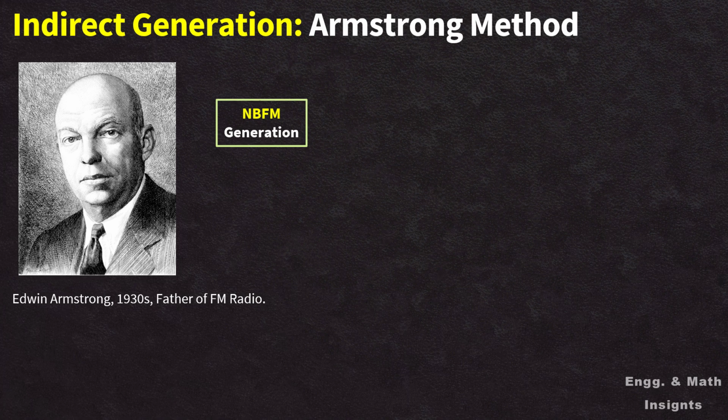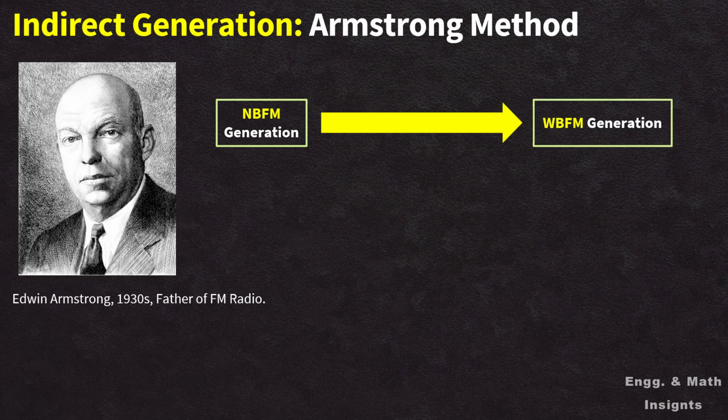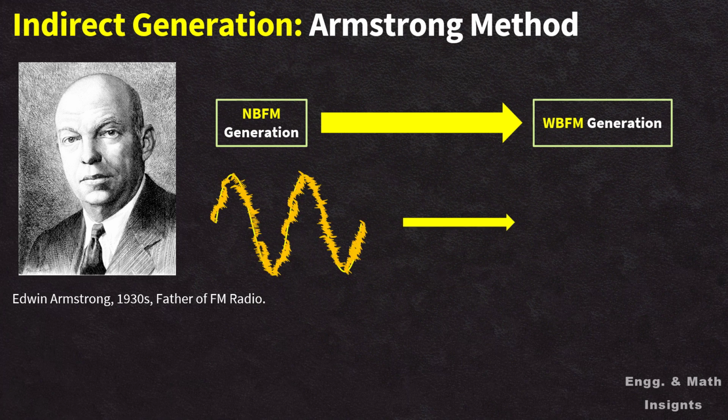Then, through frequency multiplication and mixing, this narrowband FM signal is expanded into a wideband FM signal with excellent frequency stability. Thanks to this innovation, FM broadcasting became practical, reliable, and far superior to AM in terms of noise performance. Armstrong's invention of FM significantly reduced noise and interference compared to AM, revolutionizing radio broadcasting.